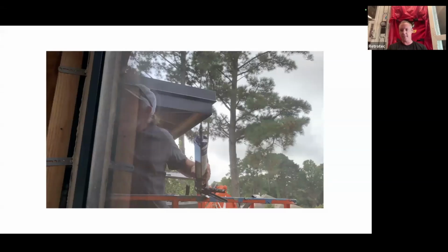Do a before blower door test, and an after, and then fog it and see what you missed. Then go back and patch up those spots that got missed, because something pretty much always gets missed. So you really shouldn't just code it and hope for the best. There's a way that you can measure it, track down where the failures are, and fix it before you turn it over to the homeowner. That really should be a standard process for everybody doing that.